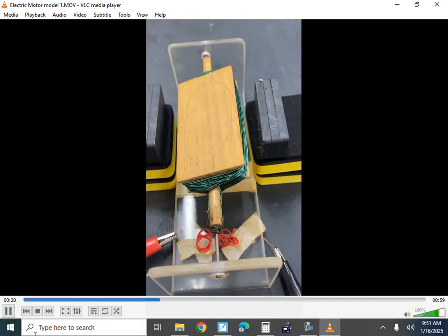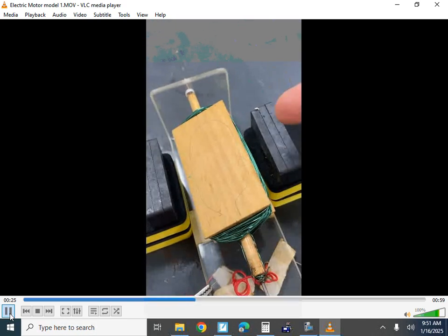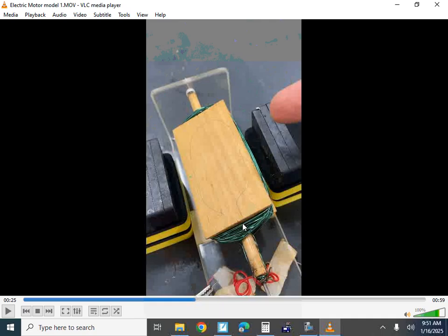And so obviously it is a real motor, but it's not very functional. The difference between this and more functional, mass-produced, more capable motors is that instead of just having one coil of wire, they have multiple coils of wire. If I had a version going perpendicular to this, there'd be wires here, right? And so you'd get the electric force causing the motor to turn happening 4 times per cycle, or twice per rotation, instead of just once. So it'd be stronger, more efficient, more effective.